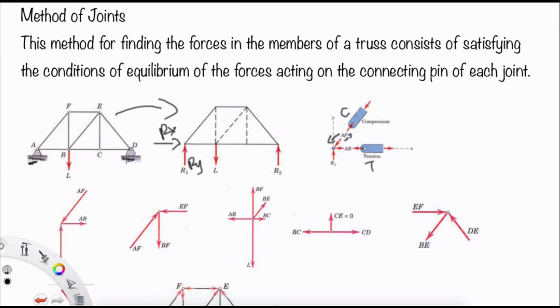It's a pin and it's a roller, or a rocker, or some kind of slip joint. Why do we find this? The slip joint, roller, or rocker is very important at one of the supports to provide for expansion and contraction due to temperature changes and for deformation from applied loads.